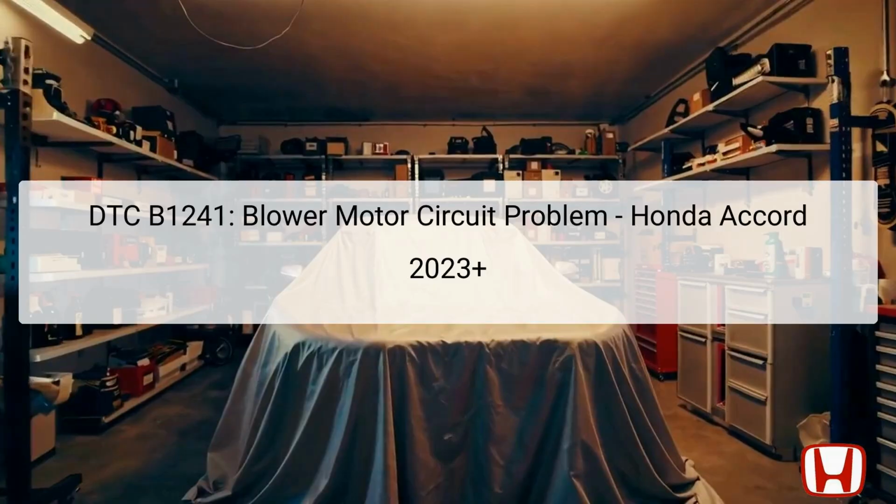The DTC B1241, also referred to as DTC Indicator 59, indicates a problem in the blower motor circuit of the 2023 Honda Accord. This issue is detected when the blower fan feedback voltage fails to fall within the target range, prompting the climate control unit to recognize an abnormality.